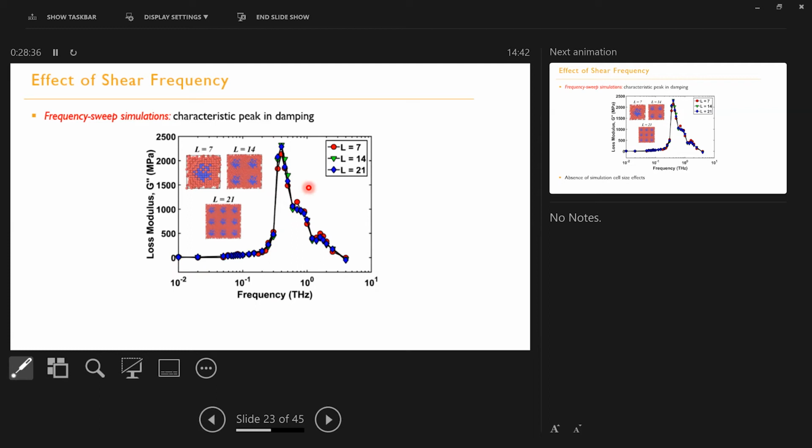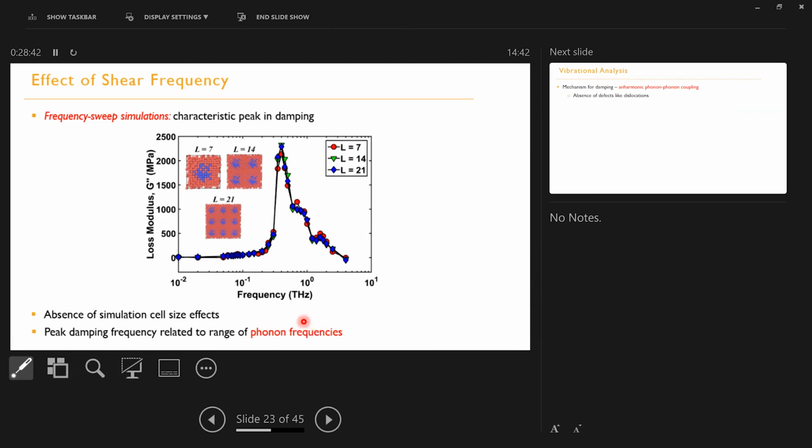This is something that's established in the literature of physical elasticity. So the clue that came to our mind is this: how many of you have heard of phonons? Yeah, everybody has heard of phonons. These are lattice vibrations. They're responsible for transferring heat or sound in materials. Whenever you have a high frequency perturbation, the waves will transfer through the phonon mode. It is known that such structures will have phonons. These vibrations are in the order of terahertz. So that's the first clue that we get: somehow the phonons are responsible for affecting the viscoelastic properties of these materials.